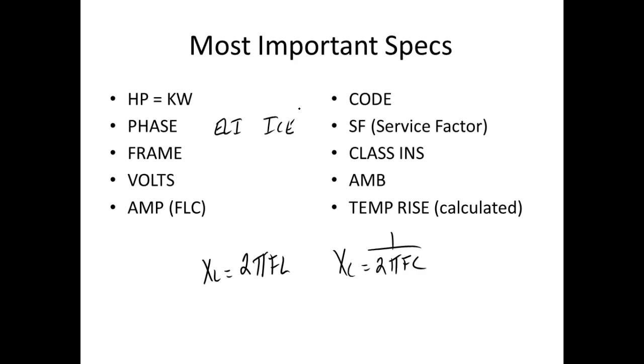because we have two types of power in an AC circuit. What are the two types of power? We have real power, also referred to as true power. And then we also have apparent power. So apparent power is how much we pay for. Real power, true power, is how much work we get.